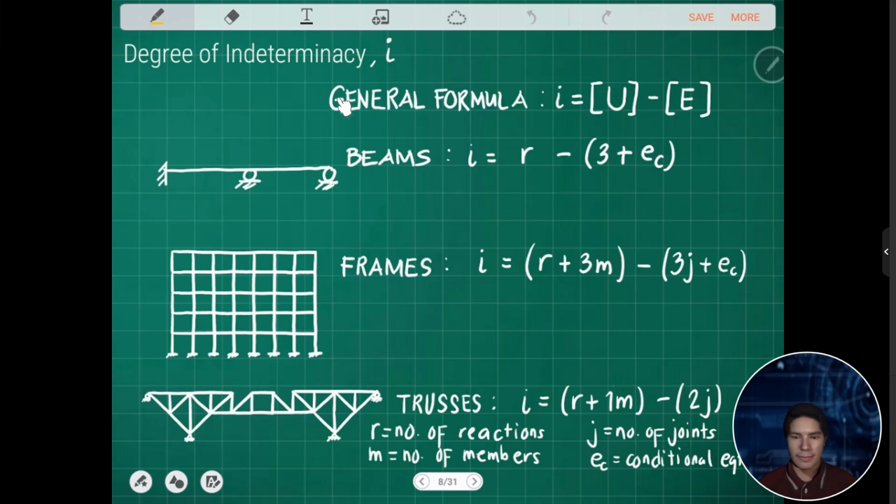So as you see here in the member, this one stands for the axial force. No? For a truss element, it only has an axial force as an unknown. So it means there is no shear and there is no moment. No? Theoretically, that is our assumption for a truss.